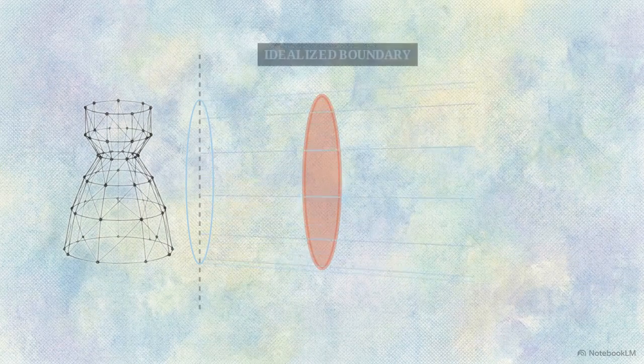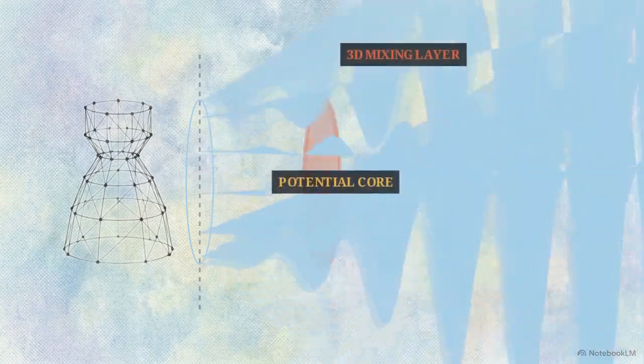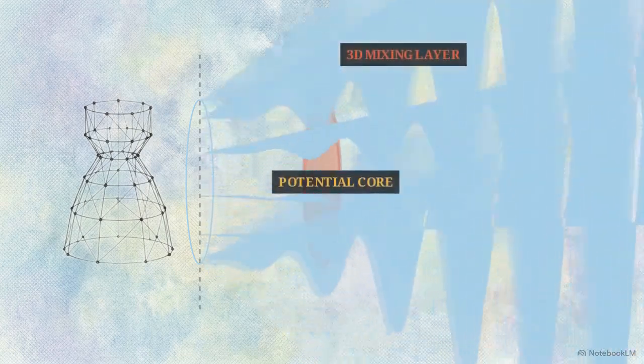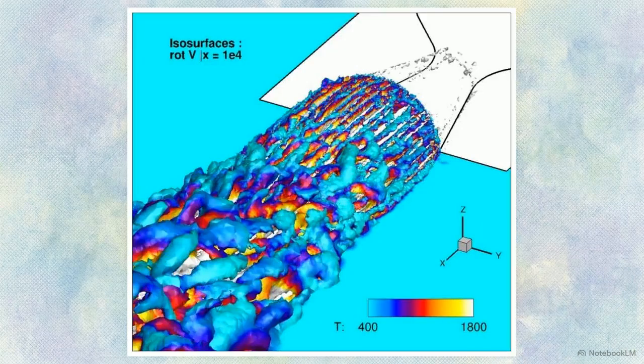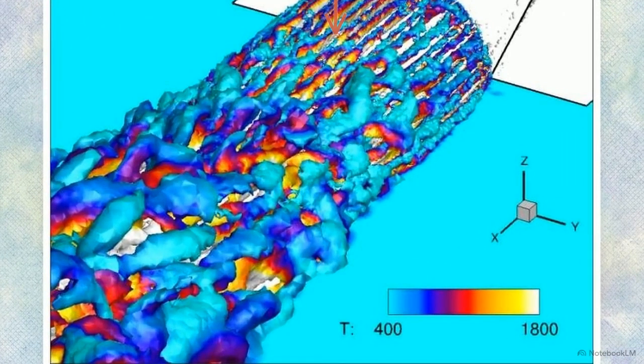The immediate aerodynamic challenge lies just outside the nozzle lip. The simulation must predict the exact spatial onset where the flow transitions into a three-dimensional shear layer. This 3D visualization displays the formation of longitudinal, Gortler-like vortical structures, predicted by the transient solvers, immediately downstream of the expansion fan. As the flow propagates rightward, these distinct longitudinal streaks physically merge.